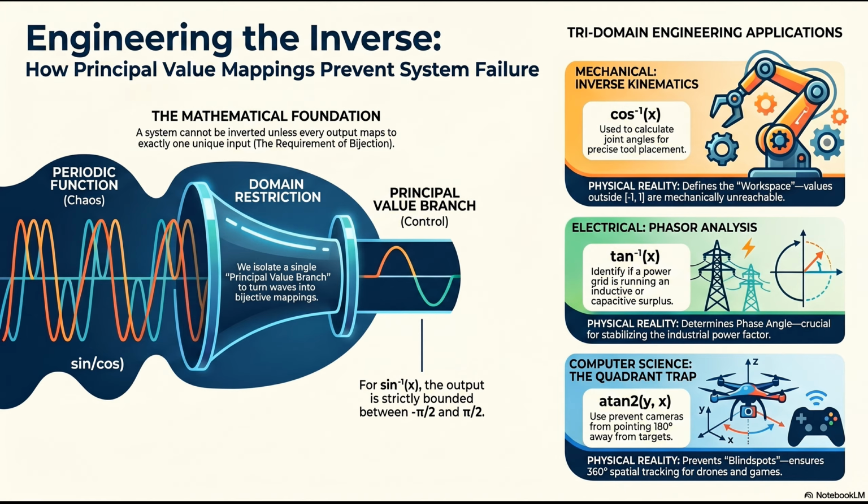Because of all those heavy factory motors. And if the angle is less than 0, the load is capacitive. The current is actually leading the voltage. Exactly. But the stakes here are massive for anyone listening who enjoys having their lights turn on. If the voltage and current get too far out of sync, the power grid becomes wildly inefficient. You are generating massive amounts of electricity at the power plant that just isn't doing any actual work. Yeah, it's just violently heating up the transmission wires, threatening to melt down the infrastructure.